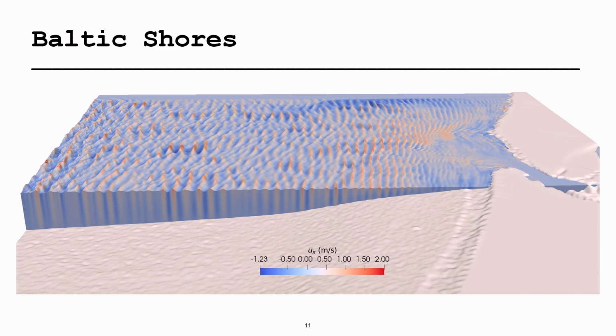The freak waves can take place in offshore area, in coastal area. It does not need to be like 30-meter tall waves, but it just needs to be much higher than the surrounding neighboring waves. So in this case, the definition basically is if you have a wave height over twice that of the neighboring significant wave height, then you have a freak wave. And this pattern really reminds me of the freak wave pattern. I don't know what it is, but due to this bottom bathymetry variations and wave interaction, you could actually have locally focused waves. That's very interesting to observe in the simulation.